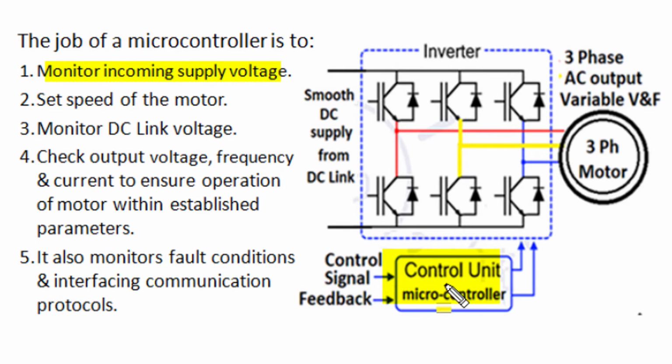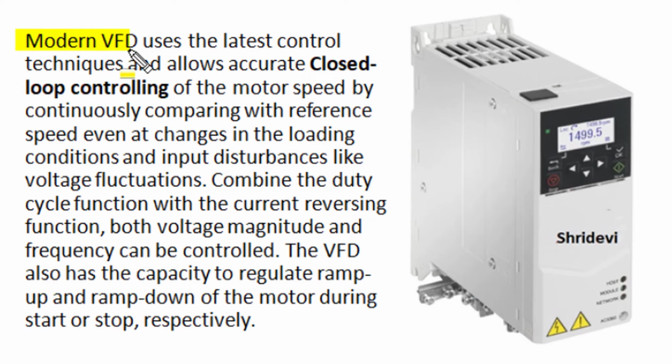Modern variable frequency drives use the latest control techniques and microcontrollers that allow accurate closed loop control of motor operation, and every time we compare the real operating speed of the motor and the reference speed.